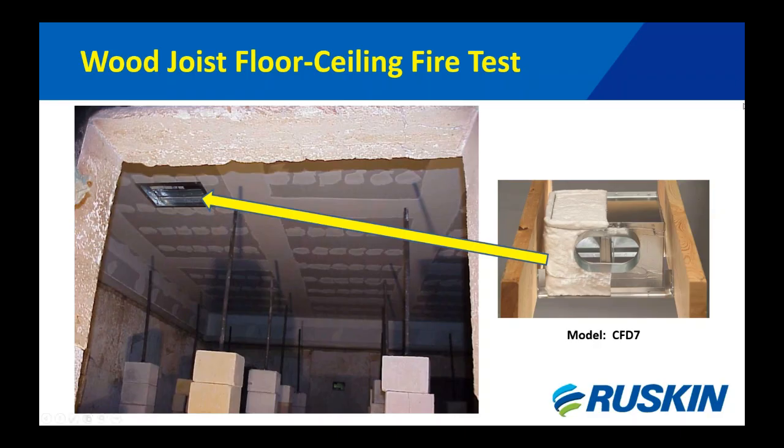So our radiation damper in this application, as you can see from the photo, we have to cover with a blanket material. So there's a steel plenum box with the blanket material that's required as part of the application. We show half of the blanket just for clarity that there is a plenum box underneath. One side reflects the blanket, how it's attached to the box, and the right side just shows a steel box. In the field, this can be applied either by the contractor or we can supply the box and the blanket from the factory. So it's an either or.